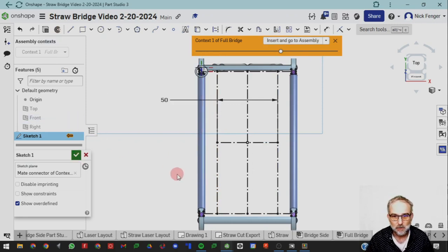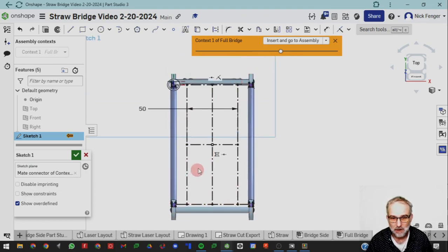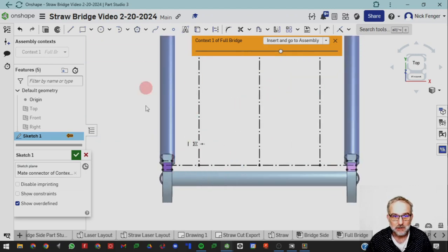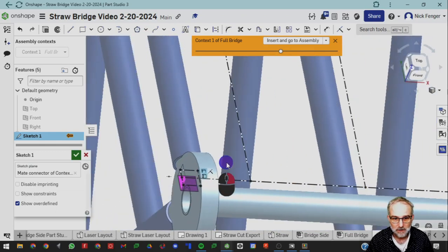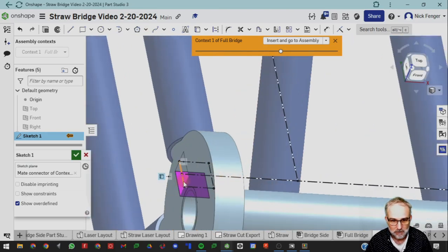Oh, sorry, no, we've got to do one part of our brace. So we're going to build a quarter of our brace, and we're going to use mirroring to put it on all 4 points around the bracing. So we're going to change the sketch over here on this end because we want to actually extrude over here. So we're going to create, because we're going to get rid of our construction lines.